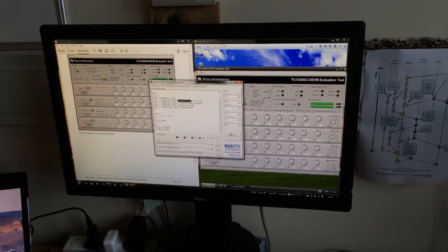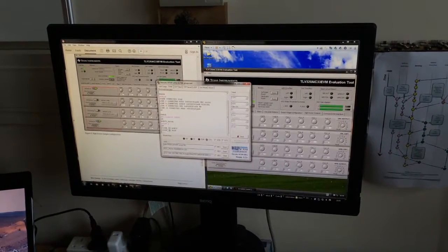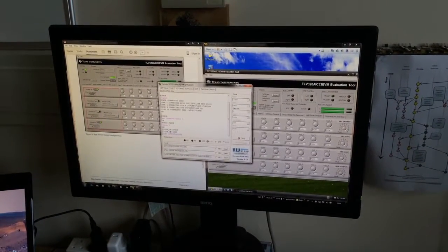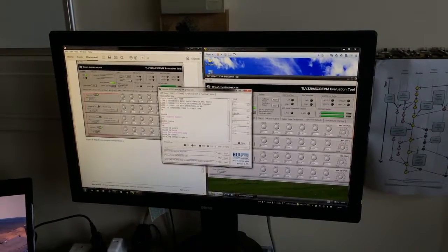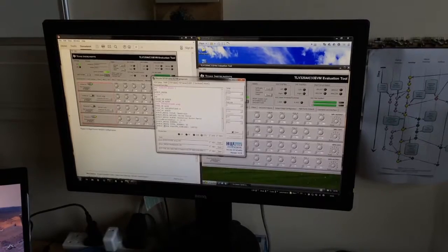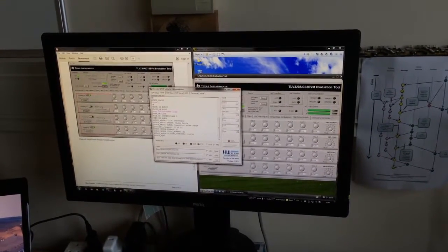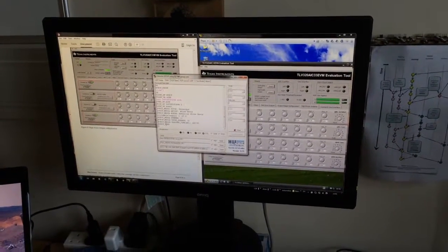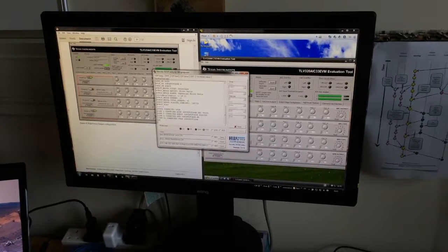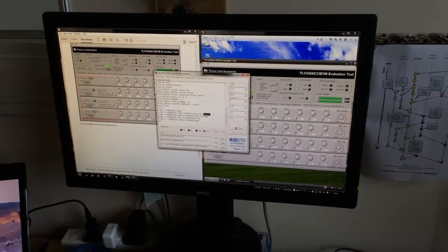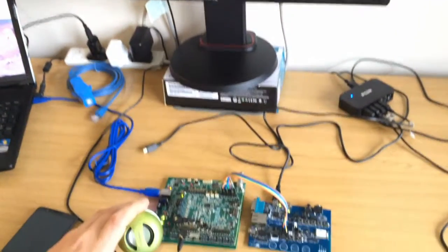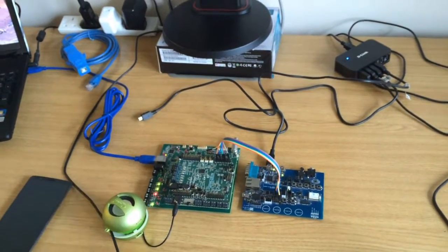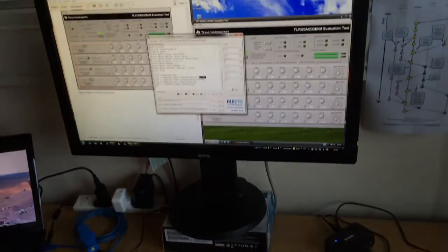The audio interface is going to be reinitialized, and if I reconnect A2DP and start playback again, we're now playing back the resampled output at 48 kHz, and as you can hear, there are no artifacts on the codec side because the clocks are synchronized with Melody.